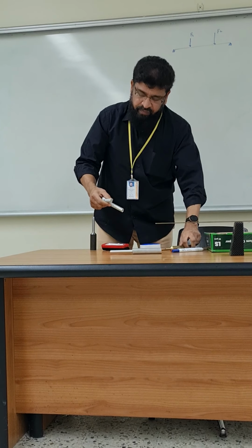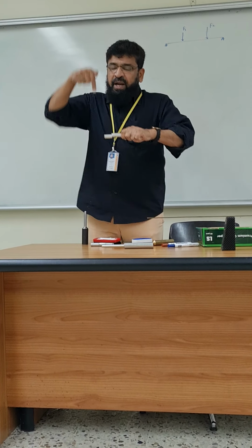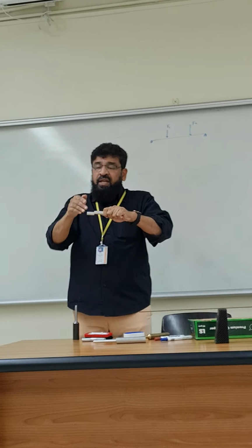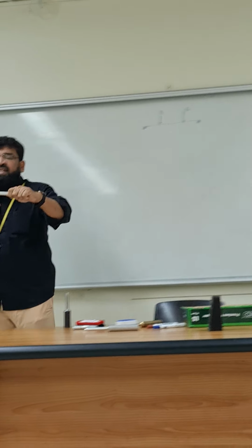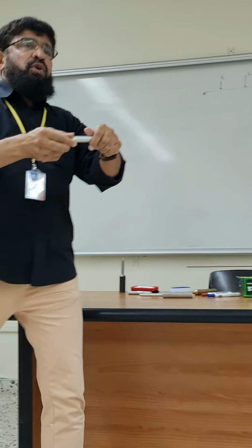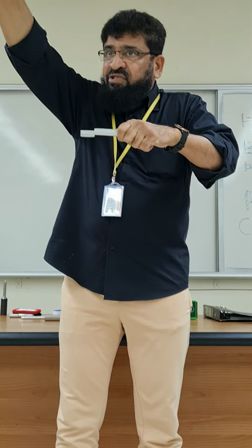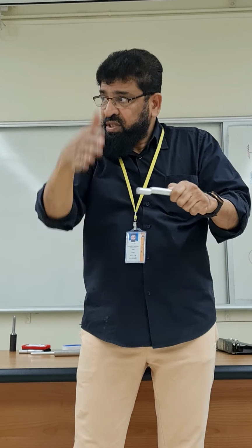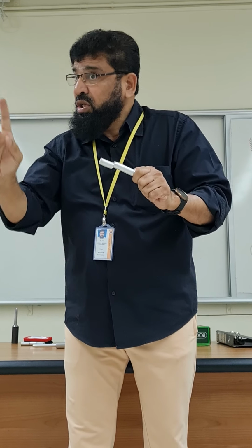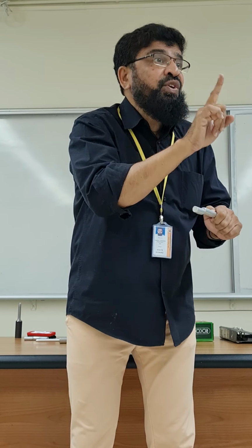See here. We applied a force. What happened to the material? The material is shearing here. See here? The material is shearing and going down, is it not? Correct? I applied a force. How much is the force? 100 newtons. So what is the shear force here? 100 newtons, is it not? Because of this 100 newtons, it is trying to shear off. I am not talking about shear stress. I am talking about shear force. Okay? It is shearing here.